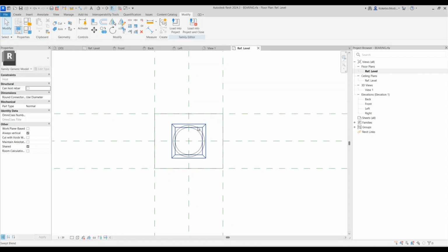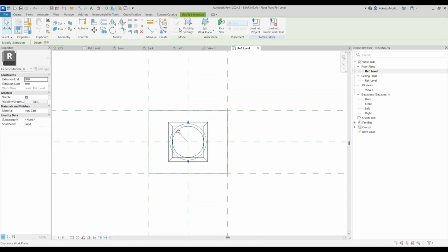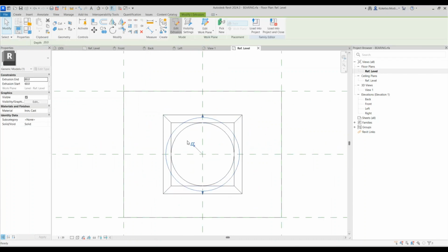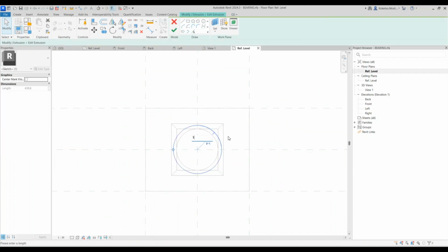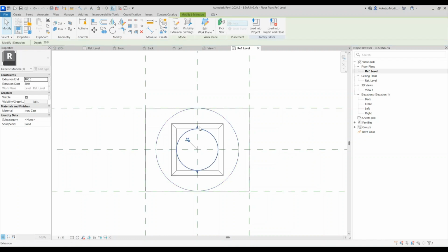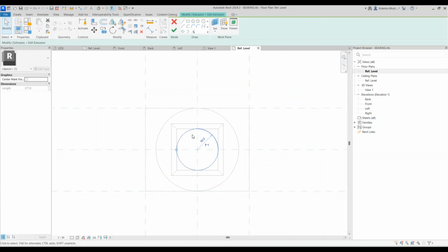So I'm going to drag this, drag this. Okay, for our plates, I'm going to increase this and make it 100 or 120. Yeah, 120 is fine. Say finish, and then the second plate, I'm going to increase it also. I'm going to make it 100.